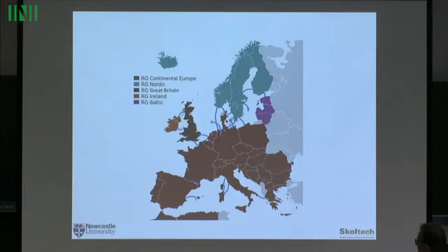Well, they have an additional effect which I mentioned before. They separate from the frequency control point of view, but the main reason is physical, is technical. Those cables which are tens of kilometers long cannot be AC because of the capacitive current effect. They have to be DC.